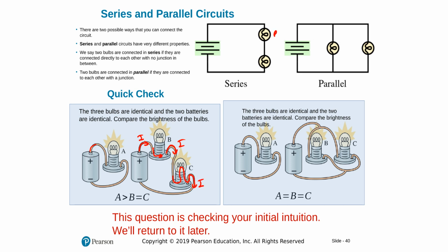If I call this one R1, this one R2, this is the symbolized circuit we see here and there. Currents will be equal to each other because we have just one line the current can go. So I1 is equal to I2, and they're all equal to one current, we can call I total. Potential differences are shared. So for a series, currents are the same.